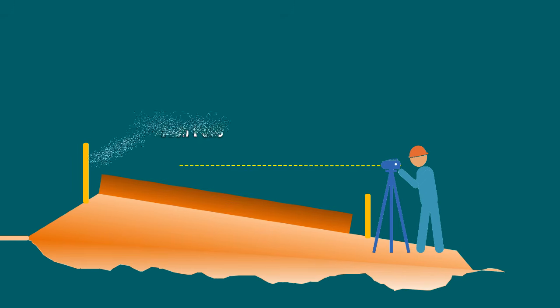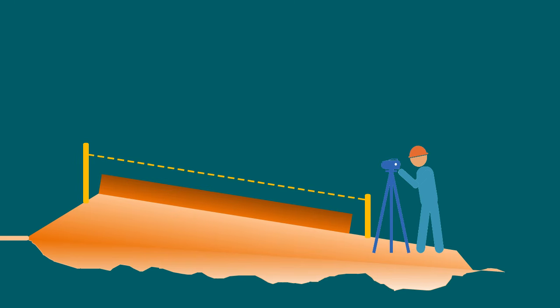The width of pavement for toe line shall be calculated by referring to the drawings, with due consideration to formation width, plus the offsets and slopes of different layers' depth, and the current layer from the formation road level. Control pegs at every 10 meters shall be fixed on both sides of the bed, in such a manner that they are not disturbed by grader movement. And 5-meter interval pegs are suggested on curves. The required level of pavement top shall be marked on the pegs, with a suitable vertical offset.